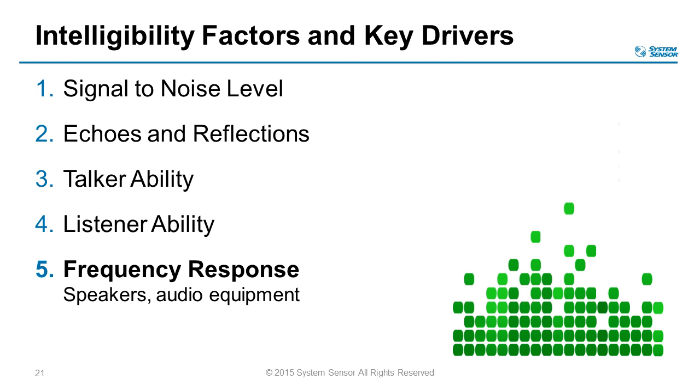Ideally, voice evacuation speakers should have a wide frequency response. The wider the response, the better it is at reproducing the signal that was introduced into the system, which obviously will provide a better opportunity for it to be understood. The frequency response should be as flat as possible, so not varying considerably. That means that you shouldn't have a lot of changes in inflection on that voice message. It's important to know that UL 1480, which is the standard for fire alarm speakers used for voice evacuation systems, requires that speakers be listed at a minimum range of 400 to 4,000 hertz.